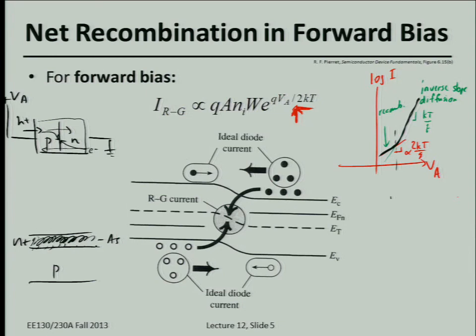So that's a good question. You heat it up to, let's say, 1,000 degrees Celsius, and that's what's done. Actually, nowadays we just melt the surface for a brief period of time, a millisecond. And if it cools fast enough, the dopants are frozen in. They don't come back out of the lattice. But you're right. With the melting approach, if you freeze it, but then later anneal it at 600 degrees, some of the dopants will come out. So you have to avoid really anything above 400 degrees Celsius. You get super high dopant concentrations activated because you originally melted the layer.